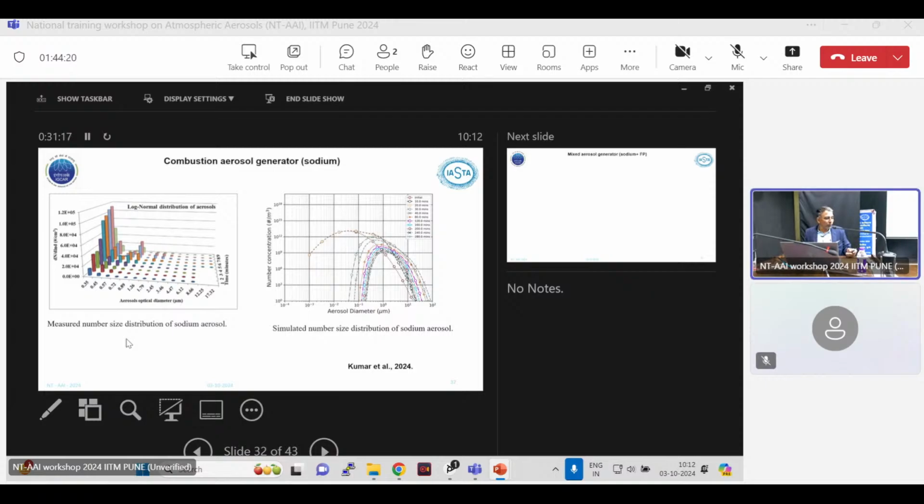So somehow we have a laser diffraction based instrument where we can collect these particles in a non-dissolving media and analyze. Here we can analyze from 10 nanometer to 2 millimeter, 2000 micrometer. So that technique only is applicable. We tried to use it with dilution OPC, but it stopped within 9 minutes because it is saturated. Concentration has exceeded its limit.